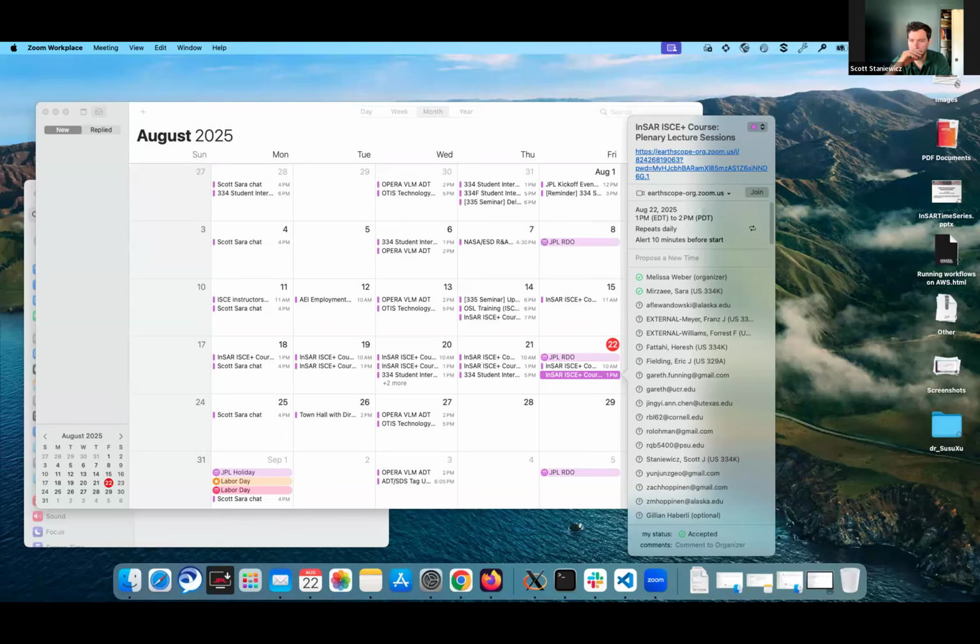You might want to say what you can do in MintPy once you have this linkage between the two softwares. True. So describe where it fits in. Dolphin, or Opera, takes in co-registered SLCs already. The output is the displacement plus noise. And the Opera data has just a couple of the corrections you might want. So it has the ionosphere, if you want to do very long wavelength corrections, or it has the solid earth tide, the cyclical corrections.